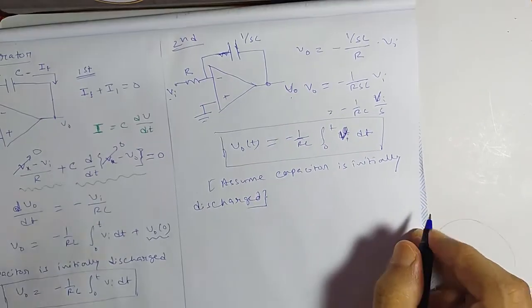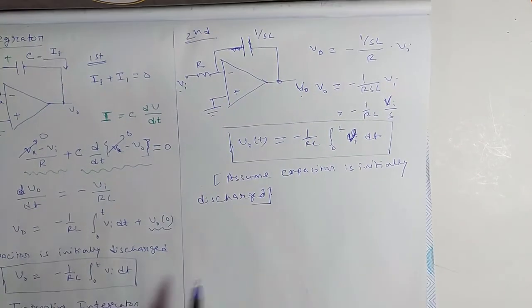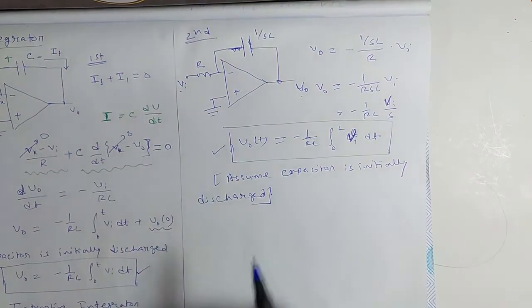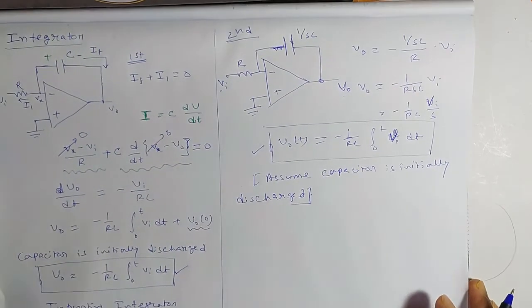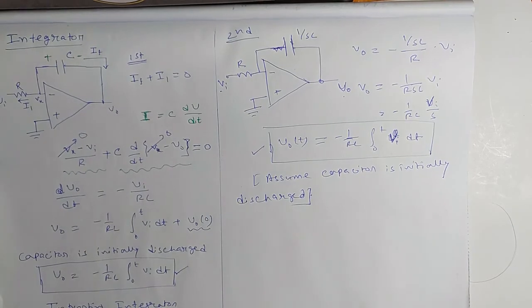Now why do we do the second method? We can get the same expression, that expression and that expression are the same. Still, sometimes we prefer the Laplace domain representation, because in the Laplace domain the differential equation solving will be very simple. So that's why we do the capacitor and integrator based circuits. We convert this capacitor and integrator circuit into the Laplace domain, and we do the analysis. Now, these are the inverting integrators. Second, we'll discuss the non-inverting integrator.